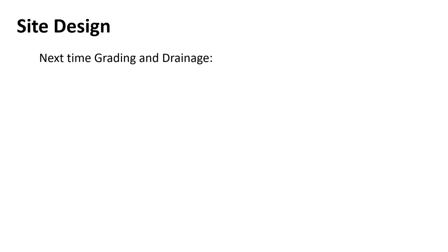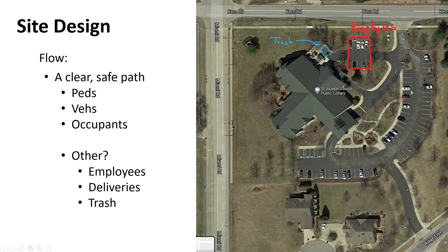Site design, even though a site like this doesn't look that big, just doing the grading plan on this is probably more than a week if you did it right. Well, maybe I wasn't doing it right. But when I would do site designs about this size, it takes quite a long time. You're going to iterate through this, and then you think you've got it all solved, you'll solve this part, and then you suddenly realize that you've got a 7% grade on the sidewalk over here. Can't have that, so you have to redesign everything and get it right. So they can be very tricky. Don't be misled by small sites.